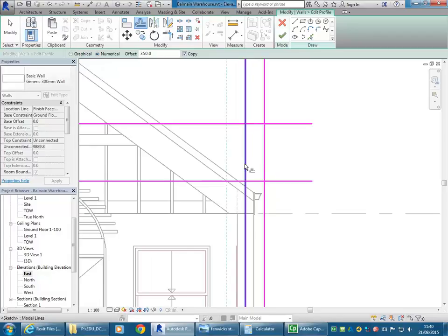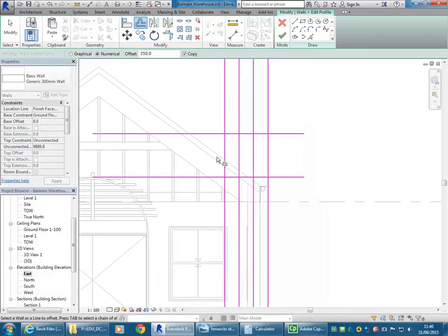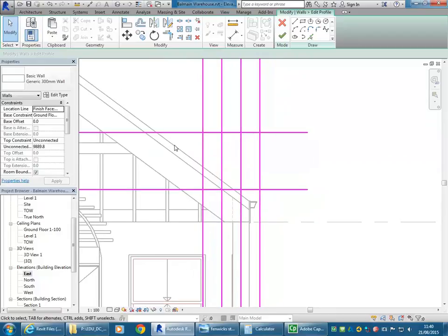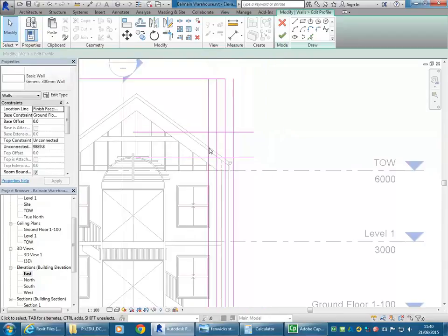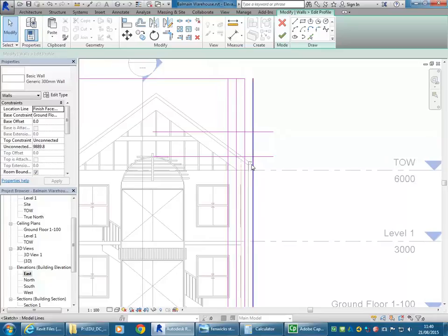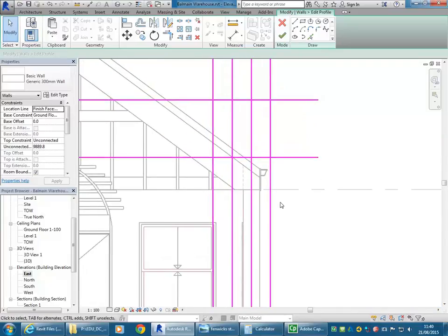So just doing 2 lines. And really, you probably don't want to try and follow exactly the way I'm doing. You just want to get the basic approach to drawing, because it's very similar to AutoCAD. You can offset and copy and do all those other things that you're used to in AutoCAD. So they're all in increments of 350. Yeah, exactly.